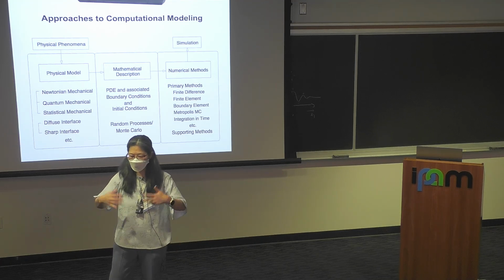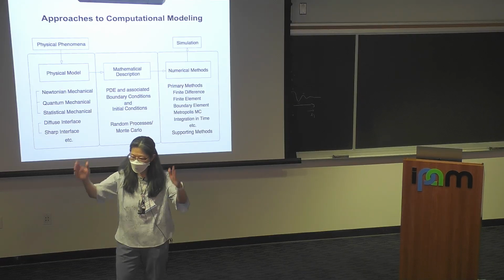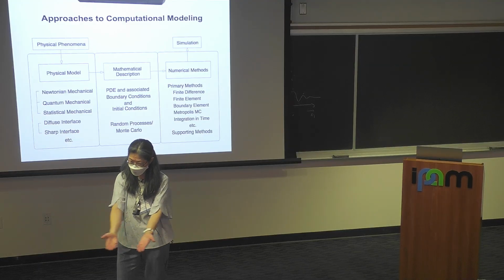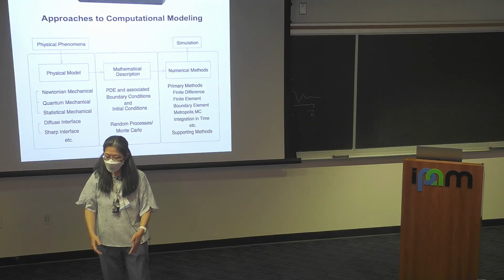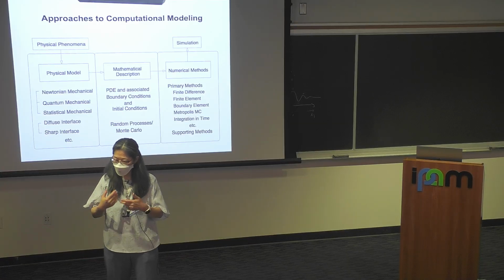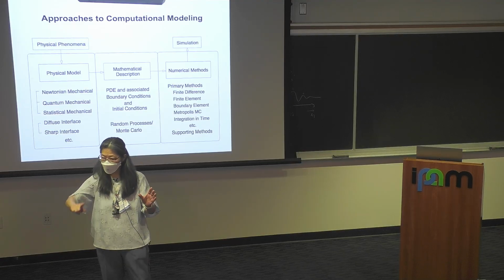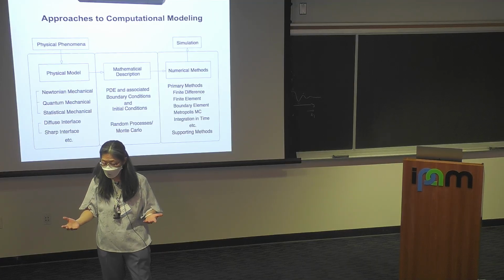If you have a mixed binary system, say, at high temperature, it's a solid solution because the free energy function looks like this. So it wants to be mixed. Now, if you quench it to a lower temperature, this free energy function can develop a double well where it wants to phase separate.